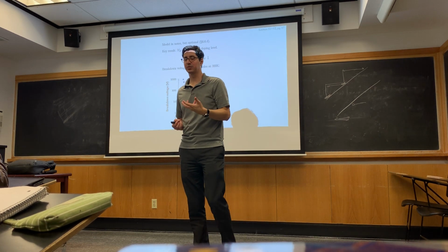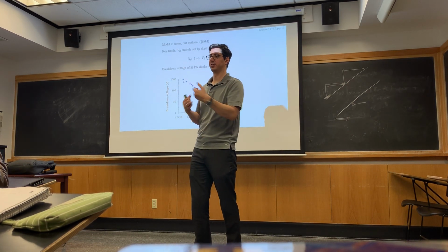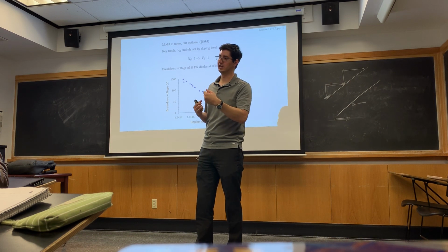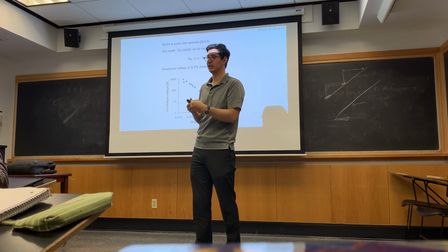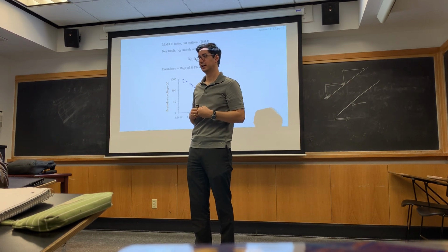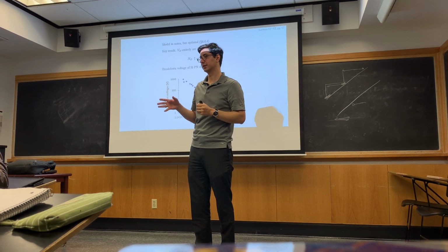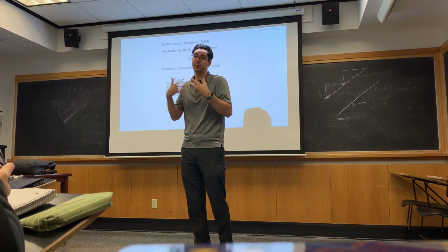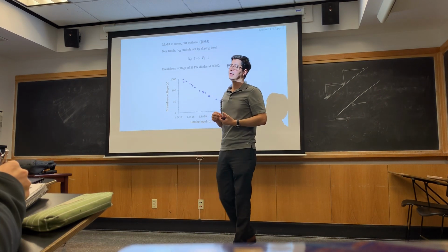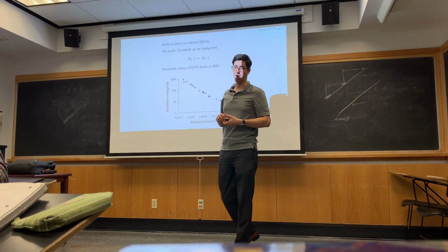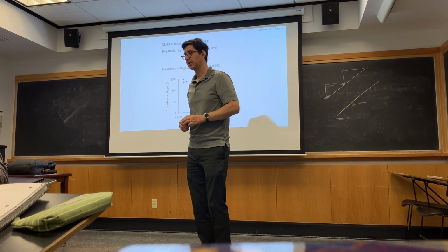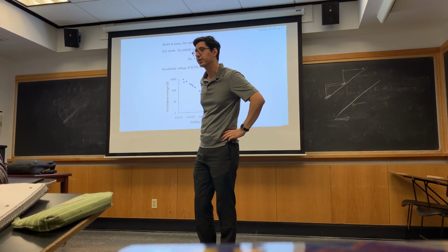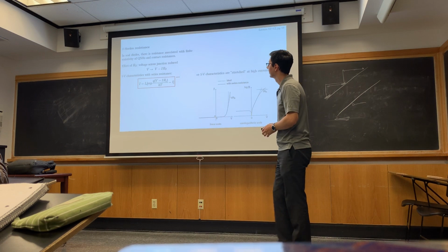Well, typically we don't think about the injection into the depletion region. We're thinking about the injection of holes into the N region, right? So we're not really even considering what's happening in the depletion region. That was our simple approximation. So it may not be completely wrong. I'd have to think about that a little bit more. Okay.